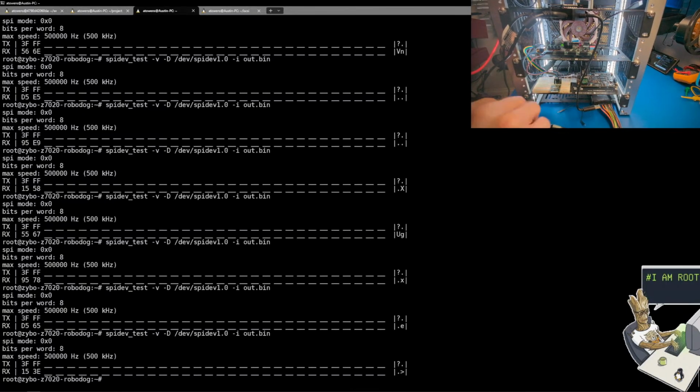Oh, man, I feel like I need a contraption or something. This is so hard. Okay, I'm gonna ground myself. I'm gonna put my ESD strap on. And I'm gonna put my hands on the board, but slightly raised above the IC.